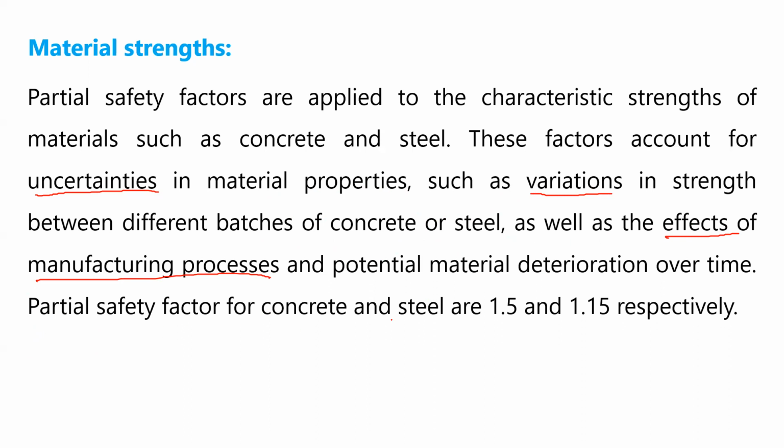Now, partial safety factor for concrete and steel: for concrete it is 1.5 and for steel it is 1.15 respectively.